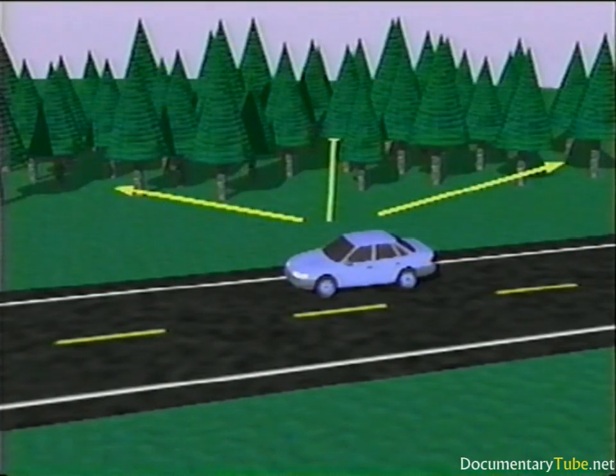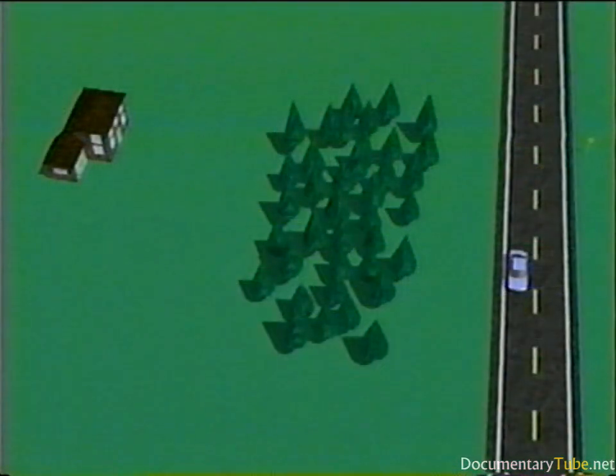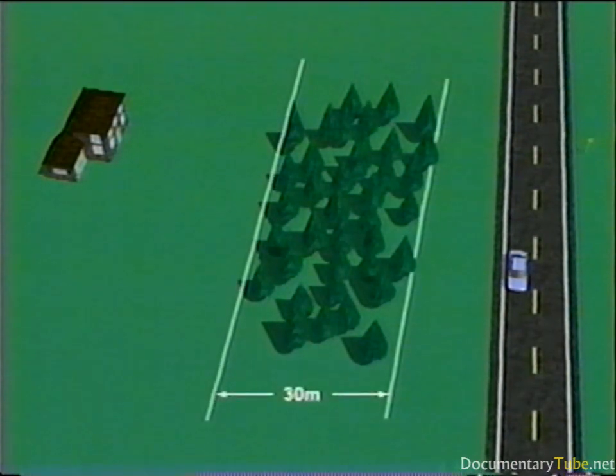In addition, some low-frequency attenuation results from ground attenuation within the wooded area, where the roots of underbrush produce acoustically absorptive soft ground. To achieve any substantial amount of attenuation due to foliage, such as trees and bushes, foliage must be at least 30 meters or 100 feet deep.